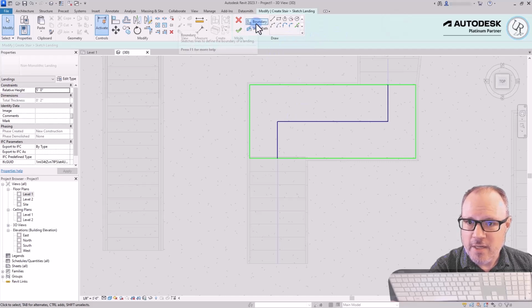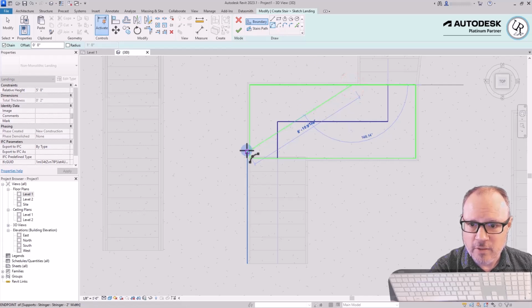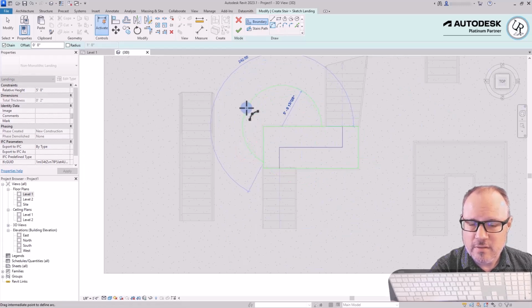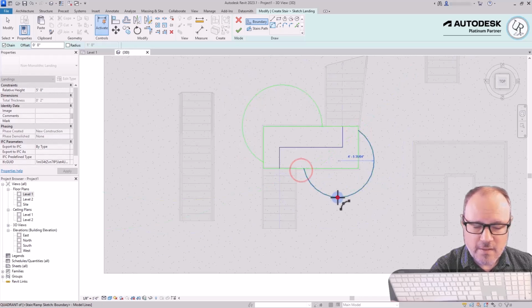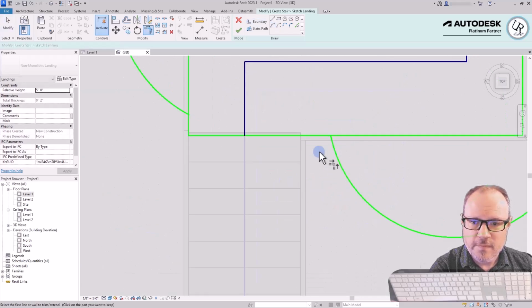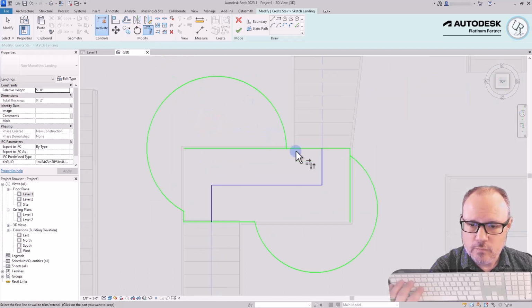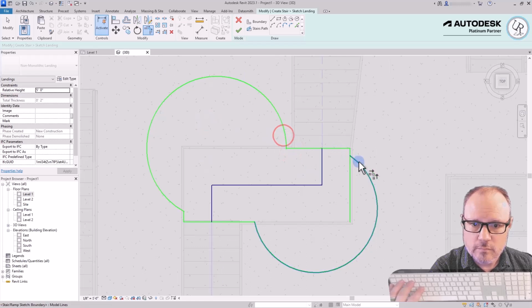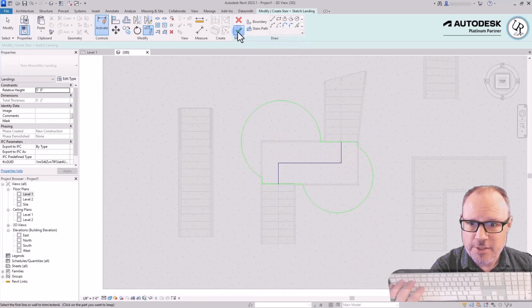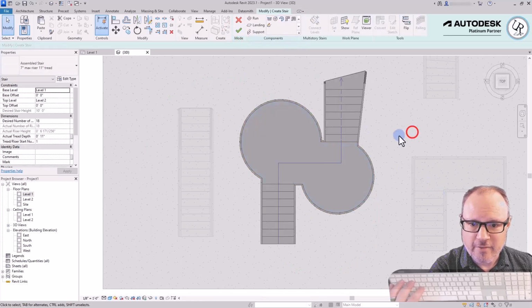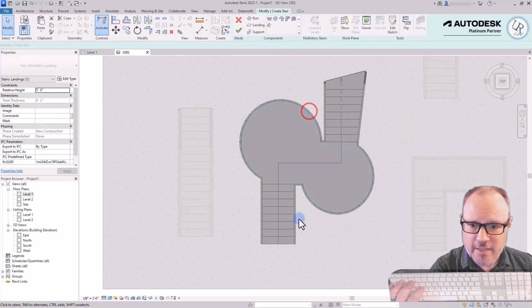And you're using boundary and stair path lines. As long as you use a boundary line and follow around the perimeter of the design, it will create whatever you need, as long as you follow the rules. If I trim those together, and then click Finish, I can make a highly volumetric area on that landing.